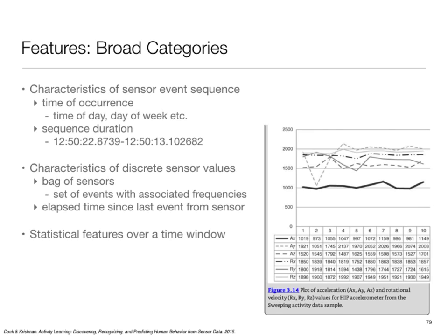So that's another way of looking at it. Then, if you have a whole bunch of values, another common way of doing these things is in terms of statistical features over a particular time window. In this case, it's accelerometer data, and I can compute all sorts of things about it. Usually you might look at spectral features, like the strength at different frequencies, or how many zero crossings occurred, or what's the peak minimum to maximum ratio, stuff like that. So all sorts of statistical features can be imagined in this context.